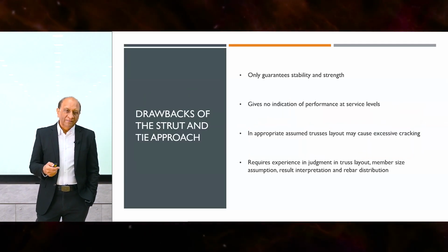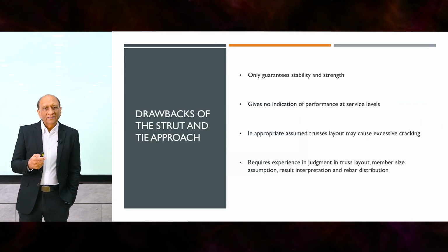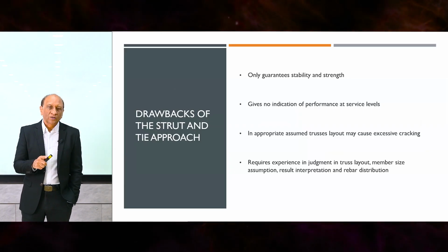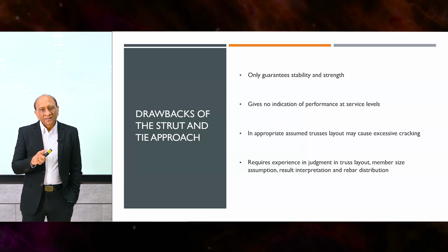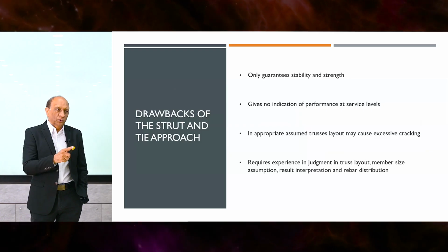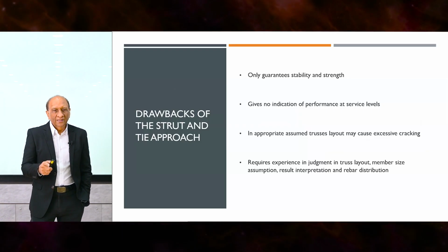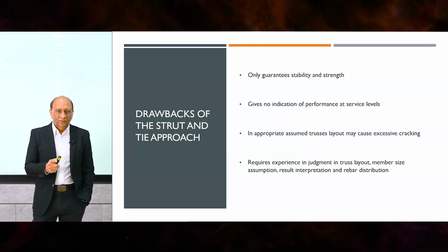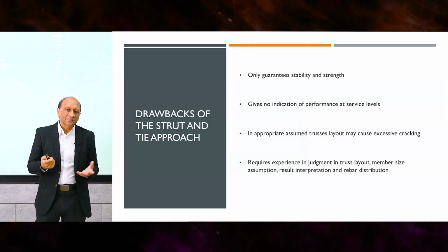So obviously, like anything that we have, there are drawbacks to this approach. Number one, it only guarantees stability and strength, it doesn't have any direct checks on serviceability. Then an inappropriately assumed truss layout may cause excessive cracking, like I showed you. If you do not size and orient the trusses well, then you can have cracking. And it requires experience and judgment in truss layout, member size assumption, result interpretation, and rebar distribution, because it's physical.